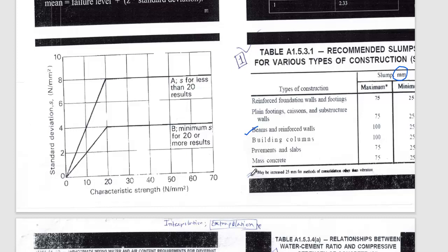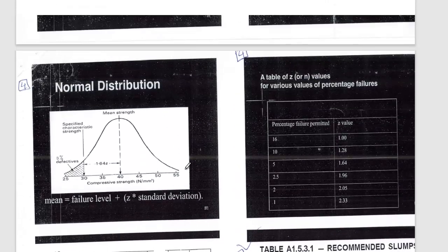But keep in mind, if you are designing some concrete where you are considering consolidation or self-consolidation, where no vibrator will be used, you can usually increase 25 mm on this range. Like where you cannot use your vibrator, that is the self-consolidating concrete. If you face any trouble, you can ask me, if you do not understand any term.